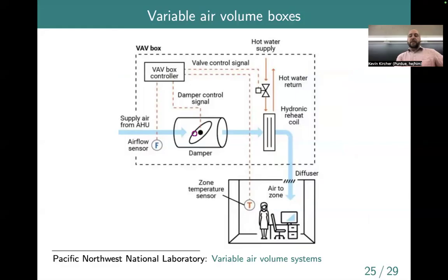Anyway, so this thing would determine, based on air quality as well as temperature needs, how much air to blow in. And then based on essentially the thermal needs, you decide how much hot water. Typically, this is a hot water system. Sometimes it would have an electric resistor in it, but how much water basically to flow through there.